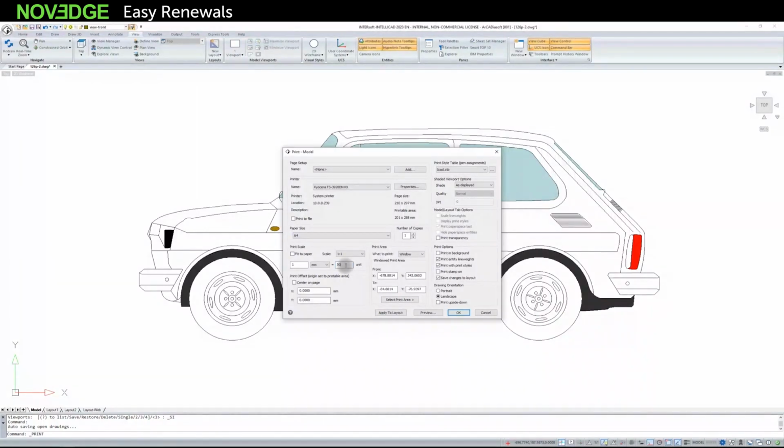scale, but right away I'll tell you that this is not the correctly entered value of the printing scale, because I drew it in centimeters, and here I have to convert it to millimeters, which means that I need to offset 10, which will allow me to print one drawing unit in 5 units on the printout.